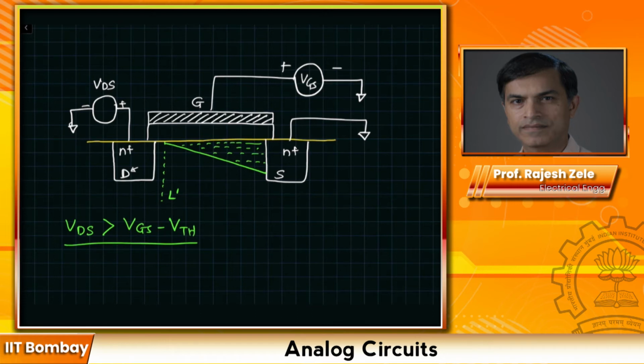So we have a very strong electric field in the depletion region, as a result of which the electrons coming at high speed from the source region are swept away across this depletion region like this. So the electrons will shoot through the depletion region and arrive at the drain. The carrier velocity of the electrons will increase a lot. So the velocity V, which is equal to drain current divided by QD, will increase. Let's try to formulate the current expression when the transistor is in pinch off and beyond.